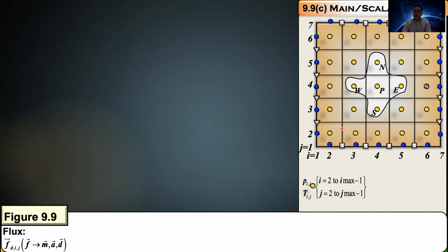In this control volume, if you are applying mass conservation, then you calculate mx on these grid points, which are shown here by green squares. And if you are applying the energy conservation law on these green squares, you will calculate qx and hx, which are the conduction flux and enthalpy flux. Note that there are 25 yellow circles, or 25 yellow control volumes, in this problem. Whereas the green squares are 6 in the x direction and 5 in the y direction. The yellow circles are 5 by 5. The green squares are 6 by 5.